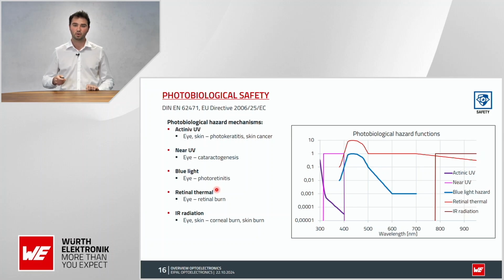For visible LEDs, the most important, or most dangerous, is the blue light hazard. There are also other photobiological hazard mechanisms like UV, which are mainly chemical processes, and on the other side thermal, so infrared radiation. If you have so much light that it heats up your cornea, then of course this will be a problem. But for LEDs, typically those two are not a problem.